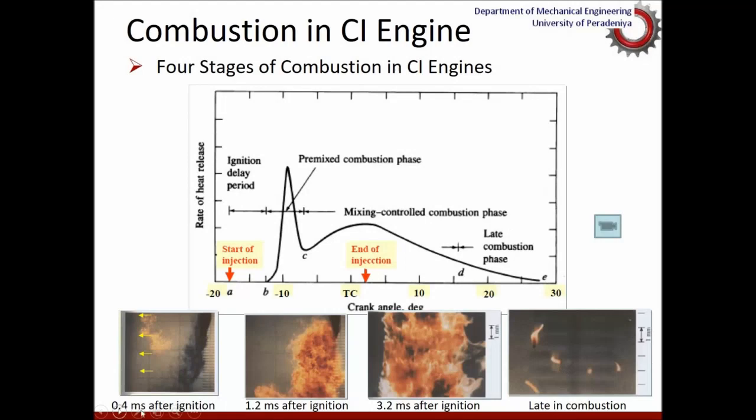Now in diesels, the combustion takes place in about 4 different stages. As in the case of petrol, there is a certain ignition delay. Then there is a pre-mix combustion phase, then a mixing controlled combustion phase, and finally the late combustion phase.